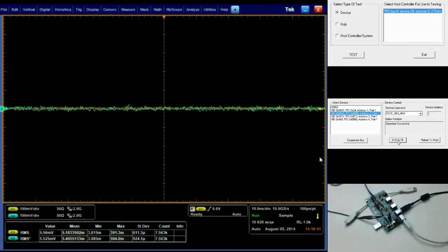In this case, what we are looking for is to measure both channels 1 and 2 at 0 millivolts plus or minus 10 millivolts. So what we're hoping to measure is essentially DC 0 volts. In this case, both channels 1 and 2 are measuring at roughly 5 millivolts, so we are again within the spec of 0 millivolts plus or minus 10 millivolts.